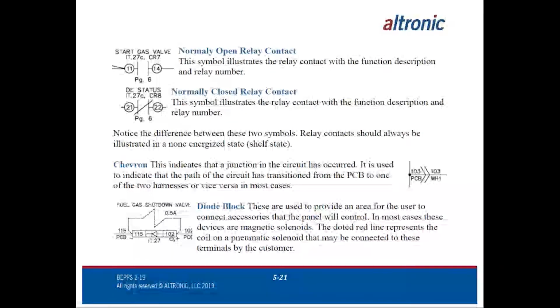Now, why is this interesting? One, we drew it out for our customers for troubleshooting purposes, just like it would be if it was a gray diode terminal block snapped on a DIN rail as an individual part. So it's easy to follow, easy to troubleshoot. But what's really interesting again about this is because it's part of the PCB, there was no physical part that a worker had to put in and wire in. The wires are already run, the wires are already connected to it. It's part of an integrated circuit.